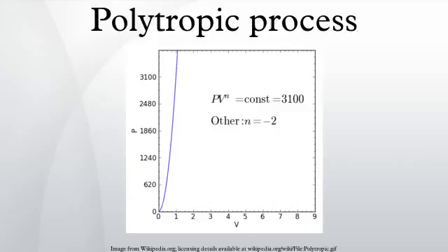In fact, the polytropic exponent can be expressed in terms of the energy transfer ratio, where the term is negative for an ideal gas. This derivation can be expanded to include polytropic processes in open systems, including instances where the kinetic energy is significant. It can also be expanded to include irreversible polytropic processes.